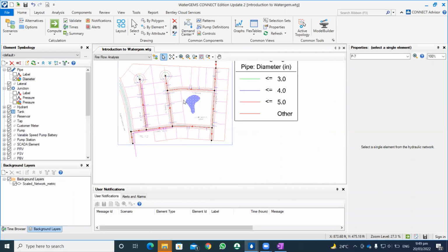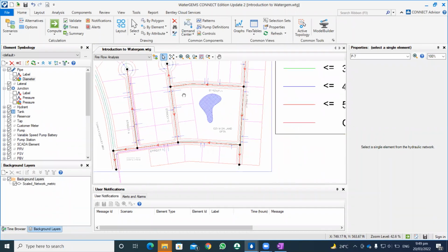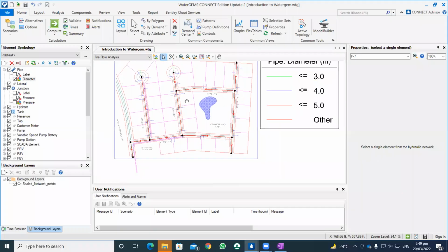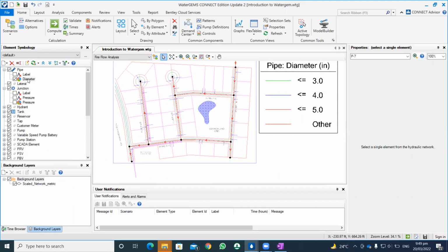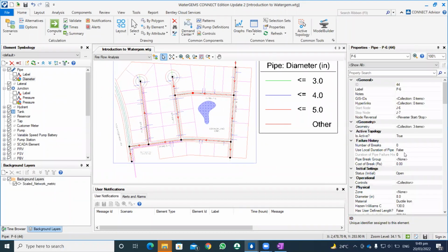So basically, most of the pipes have a diameter higher than 5 inch. Darwin Designer has calculated the diameter of that pipe about 8 inches, or about 10 inches. Similarly for that. So basically, the diameter of pipe increases because the demand at this junction increases.